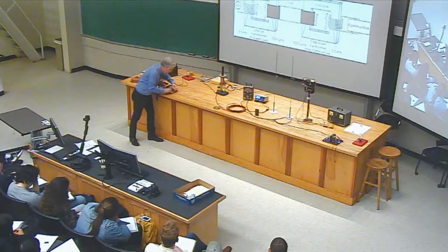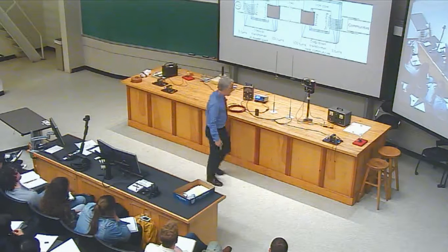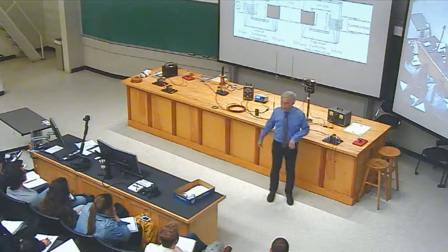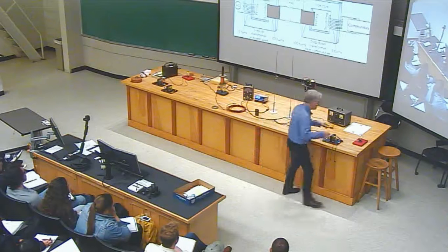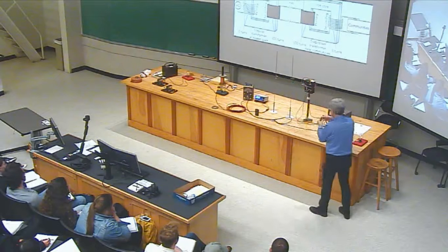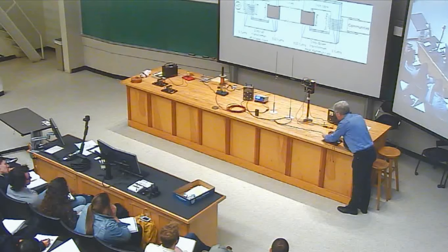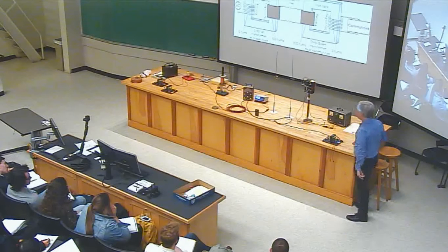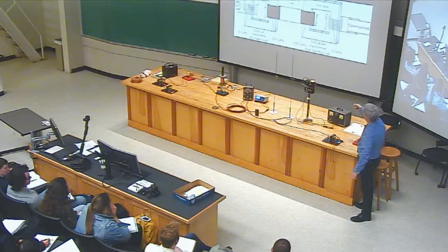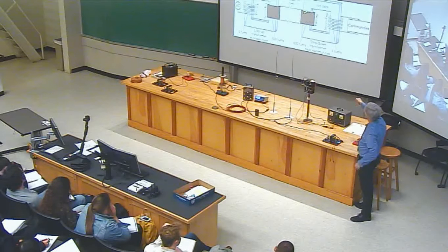There are a bunch of different choices here. This will work fine, I think. Okay, so this will now be operating with a smaller current at higher voltage. I will now take the wires here, and I can't run them directly into the light bulb. I need to go through a step-down transformer to undo what I've just done. So we've now connected to the many-turn coil, the primary of the step-down transformer.